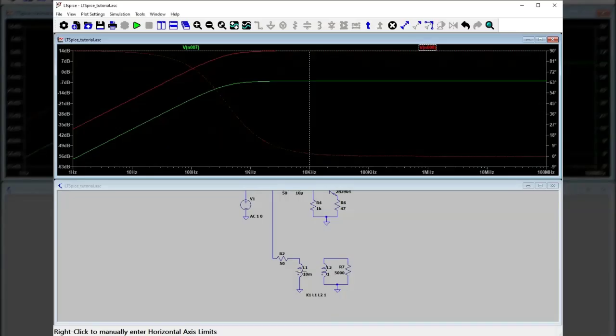Now, one last little thing here, frequency response. Remember, we said this transformer was ideal, except we don't have infinite inductance. And we can see that effect here. If we go down to 1 kilohertz, that's about as low as we can go here with the 50 ohm source and load, 50 ohm source, I mean. And if we go less than that, our frequency response starts to roll off.